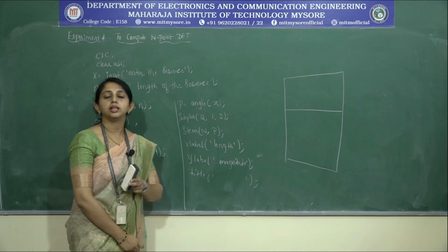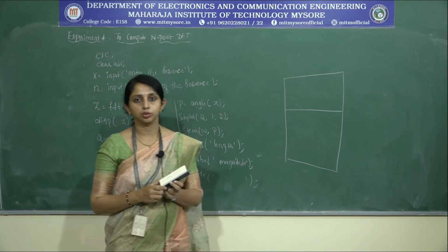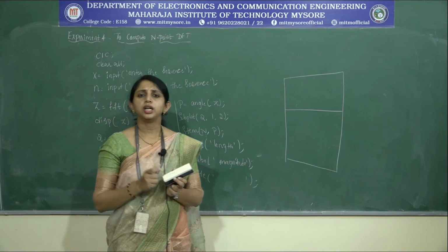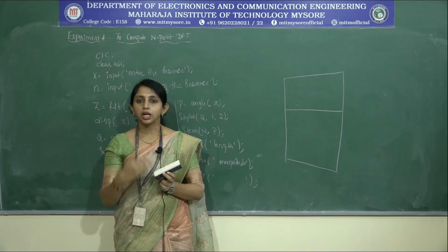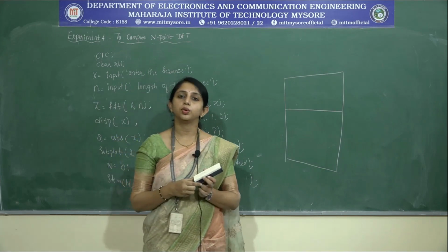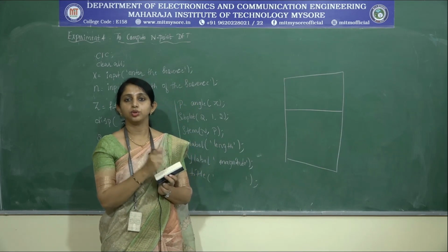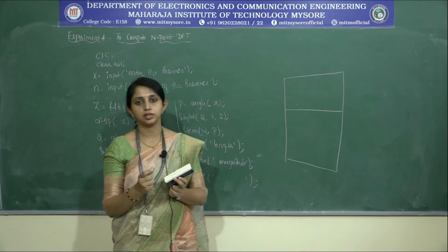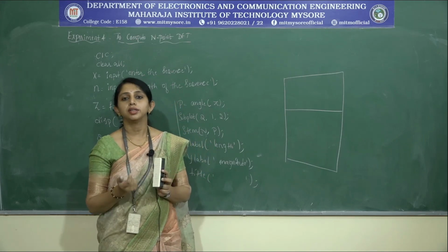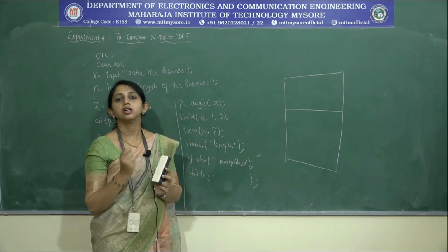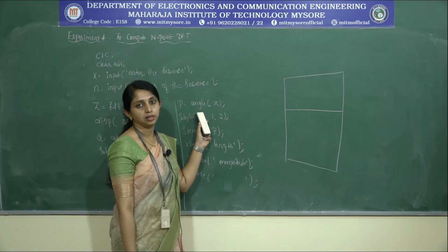How to calculate the phase and absolute values from the DFT output? The DFT output will generally be in rectangular form. If you convert the rectangular form into polar form, what values are we going to get? One will be the absolute value and another one is the phase value. For calculation purposes, you can convert from rectangular to polar to get the absolute values and angle values.